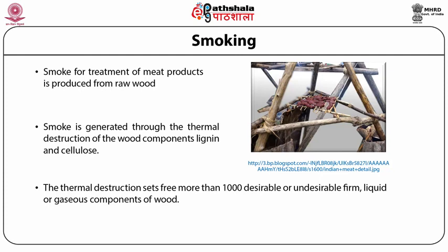The smoke is continued throughout the third stage with all dampers closed and the temperature in the house raised to 180 °F. Hold this temperature until the product temperature reaches 142 °F.